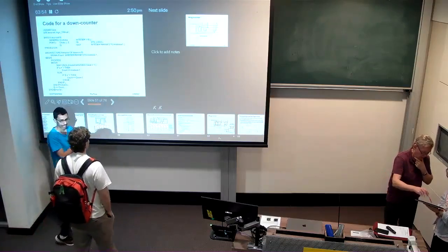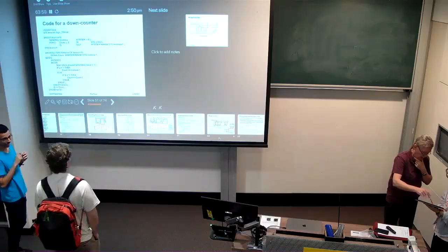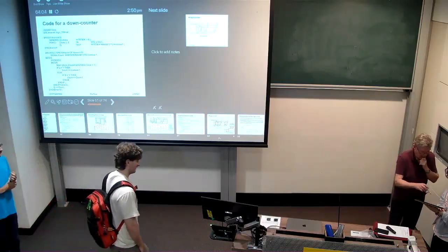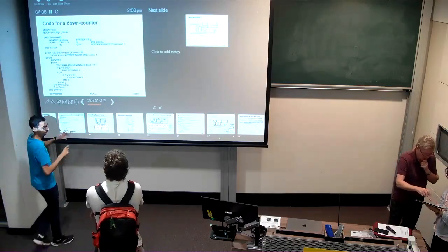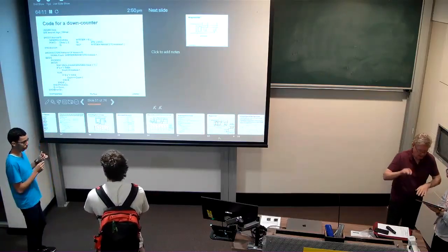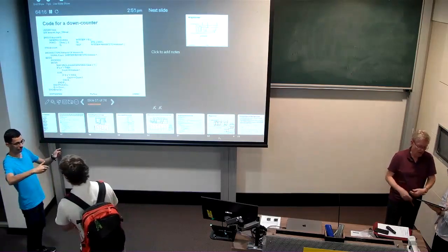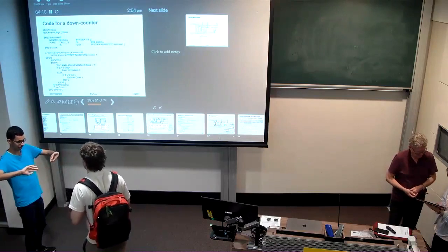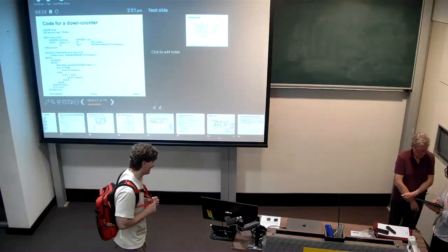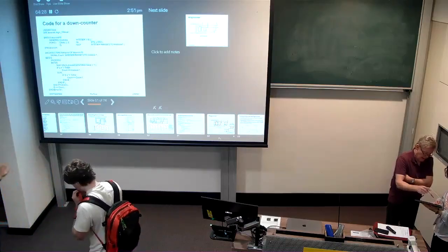Because if P2 is still 1 and D changes, then that change can come out as P4. And if that happens to be a 1 rather than a 0, then the state of the whole flip-flop is now undecided. It doesn't know whether it should change to a 1 or to a 0. Somehow it sorts itself out.